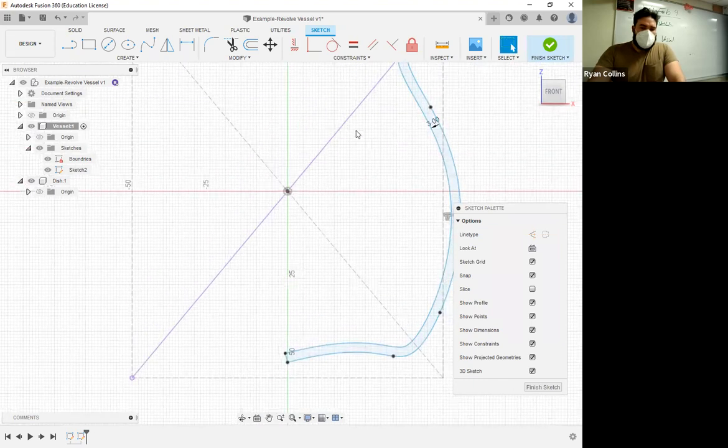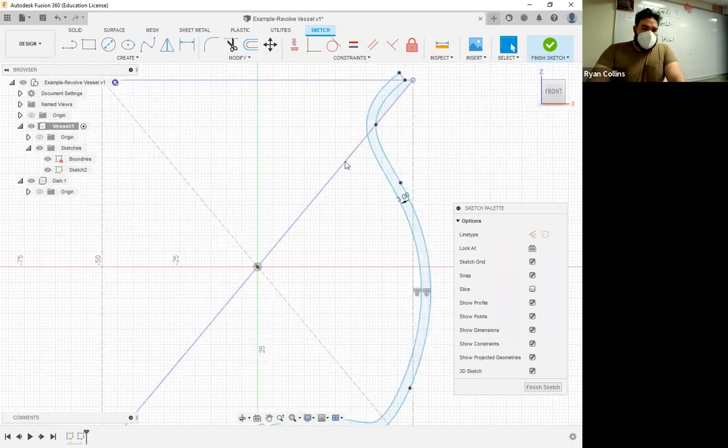Another thing, just so you know, the reason these lines have now turned purple from a construction line is that Fusion will automatically, and you could use the command as well, project lines from one sketch to another. If you are drawing on one sketch that overlaps another, but because it's visible, you interact with that first sketch.